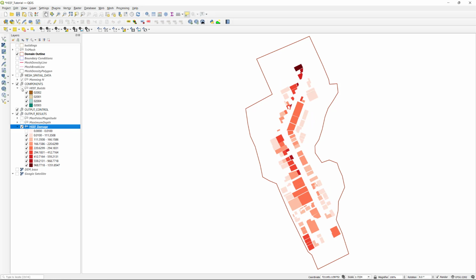The map legend in reddish tones shows the cost categories of damage to the structures. We can then generate statistics of the fields utilizing QGIS's tools. The tool can be found in the Vector menu under Analysis Tools, clicking on Basic Statistics for Fields.